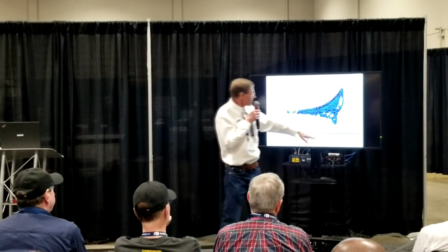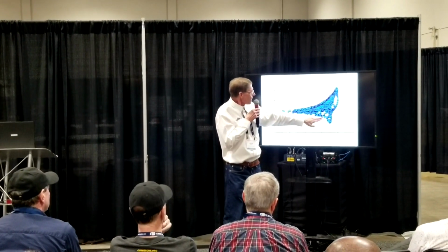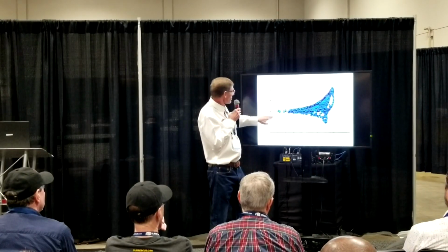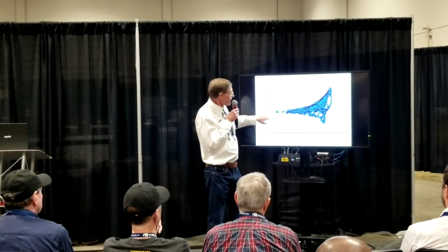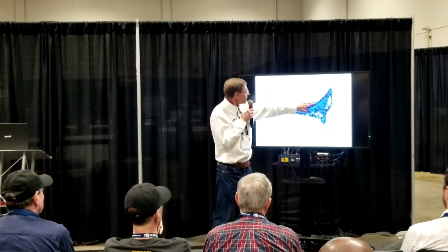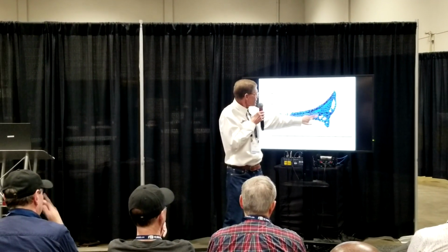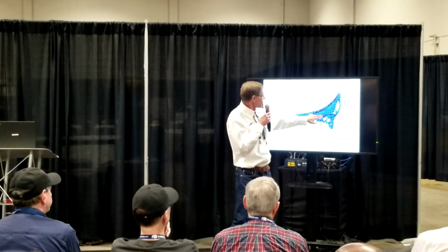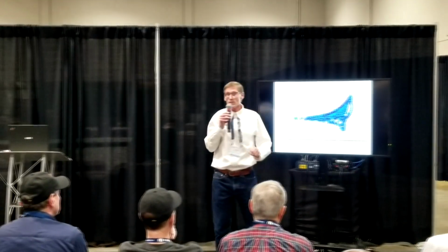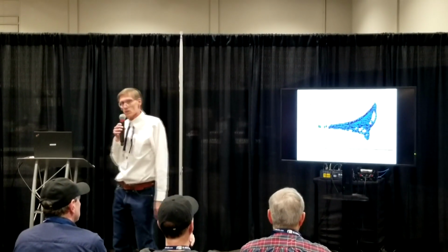Even funnier, if you come to here and I go up, take that data point, come over here, it's a 95 ohm cable. I come up to here and it's somewhere around 110 ohm cable. But all three of these different resistances, including the 100 ohm cable in the middle, all have roughly minus 30 dB return loss.